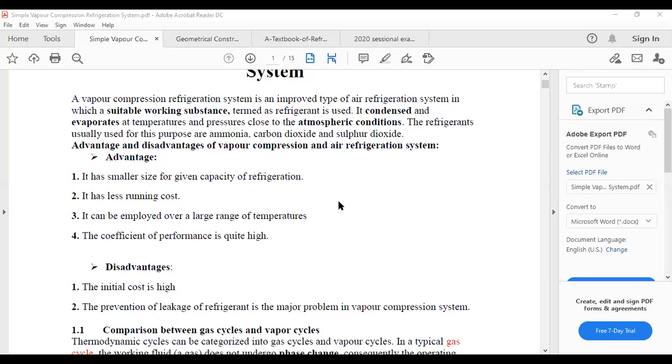It has a low running cost. Some of you who have been in homes with a fridge can't even remember the last time the fridge was taken for repairs. If you look at the fridge, the main component is a compressor, and that compressor is sealed in, in a confinement. Such compressors are called hermetic compressors. Meaning no dust gets in and nothing moves around, so they can last years without maintenance. The running cost is very low for such systems compared to the air system, where maintenance has to be carried out after some years.